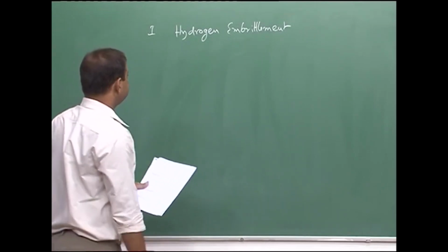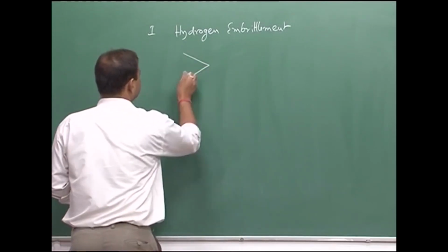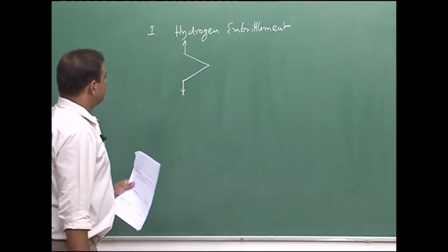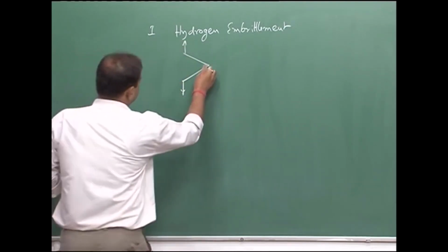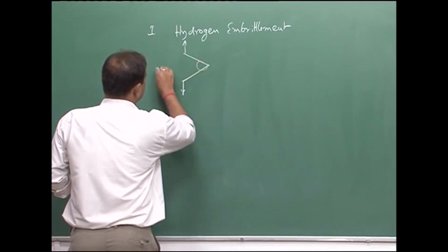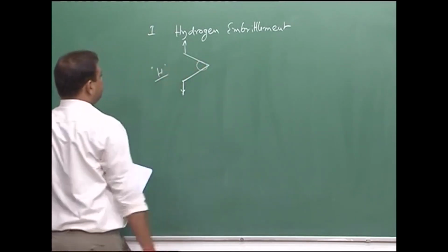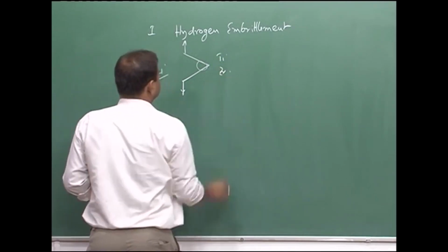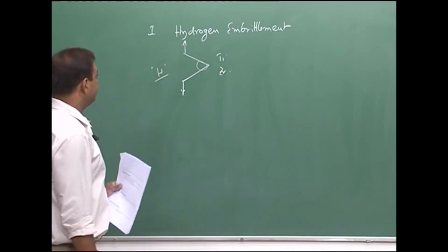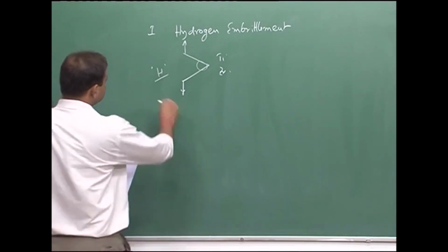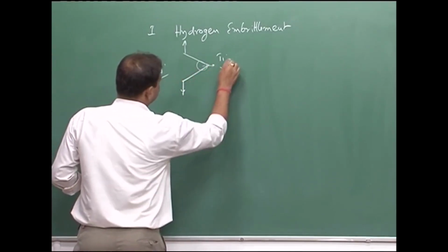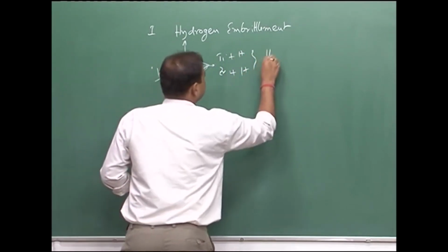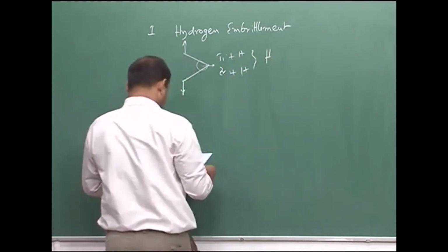In this process, let us say we have a crack like this and this crack is under tension, and in the crack tip zone you have atomic hydrogen formation, and if your material contains titanium or zirconium, those are the hydride forming elements, this hydrogen can diffuse in and react, and then they can form hydrides.